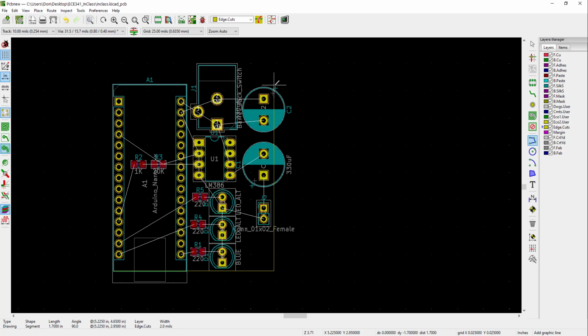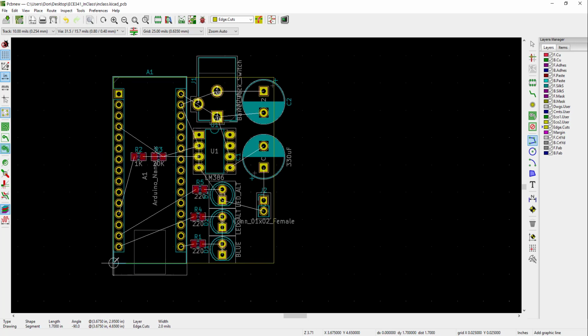And this is an important thing to remember, is that your PCBs you usually pay by the amount of material used. So, and then I touch the edge of the nano, and then I'm going to double click on my starting spot. Oops. And I now have what's called a board outline. So when I go to manufacture this, this board will be trimmed to that size.